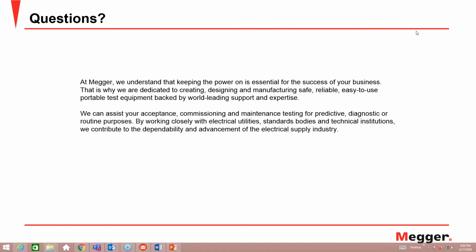All right, thanks, Andy. Volney, our next question is to you. Does battery ground have impact on battery life? Like many answers related to batteries, the question is, it depends. What a ground fault will cause is a permanent circulation of current to ground, and if the fault is in the DC system outside the battery circuit, the string, then that current may be supplied by the charger, so the battery won't be affected by that.